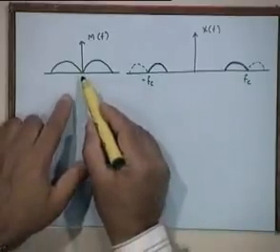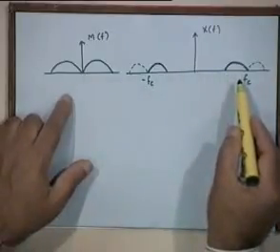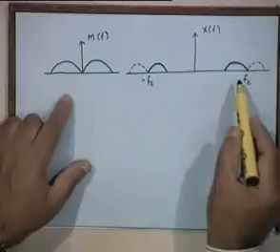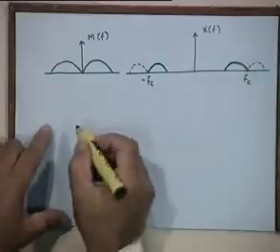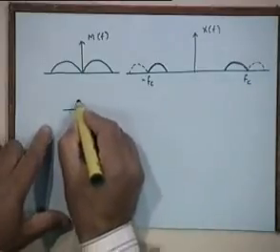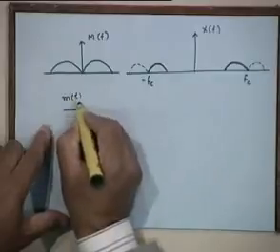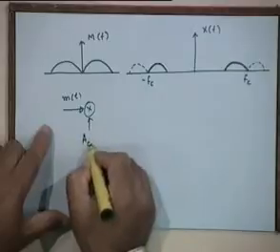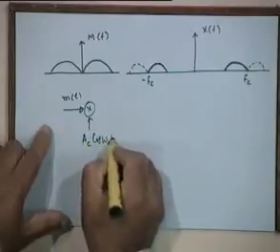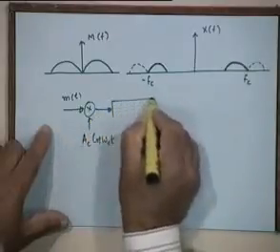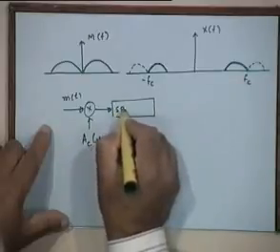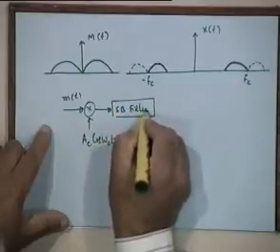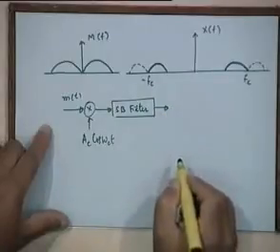You first generate the DSB-SC signal, like we discussed yesterday, going through the normal modulation process first, and then through a suitable sideband filter eliminate one of the two sidebands.